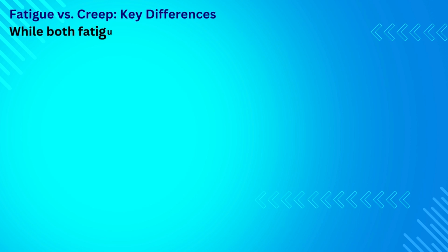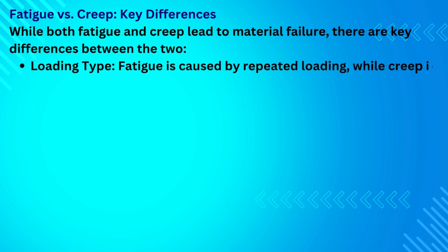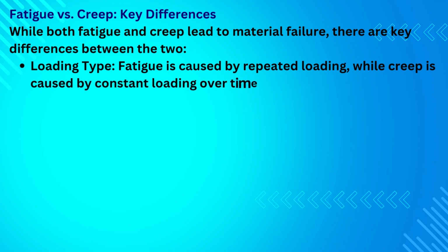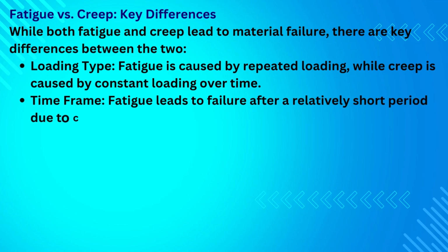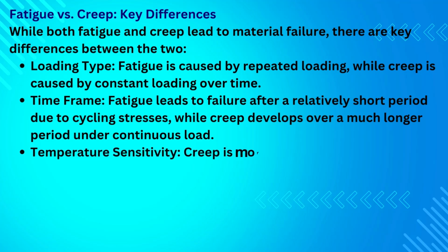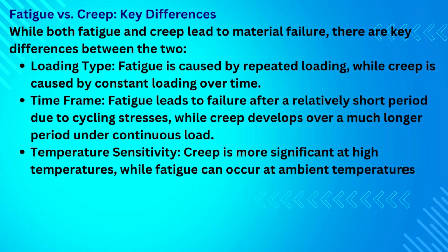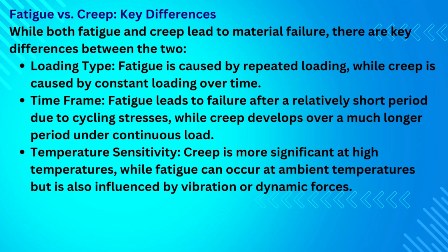Fatigue versus creep: key differences. While both fatigue and creep lead to material failure, there are key differences between the two. Loading type. Fatigue is caused by repeated loading, while creep is caused by constant loading over time. Time frame. Fatigue leads to failure after a relatively short period due to cycling stresses, while creep develops over a much longer period under continuous load. Temperature sensitivity. Creep is more significant at high temperatures, while fatigue can occur at ambient temperatures but is also influenced by vibration or dynamic forces.